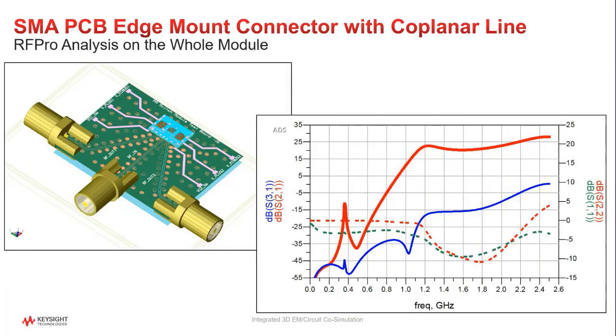Okay, here is the overall simulation results on the whole module. You can see there are a few issues that need to be looked at and improved. Here are a few of them. Number one, the PA standalone, if you remember, has 27 dB of gain. At the laminate assembly level, we lost 3.5 dB. And we lost another 2.5 dB at the test board assembly level. This 6 dB of loss seems large, and I'm sure a big part of it can be recovered by revisiting critical junctions in the assembly and reduce the mismatch losses.